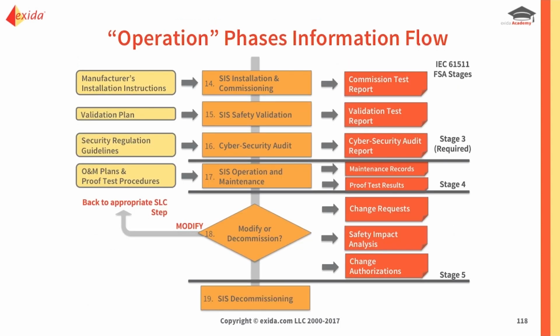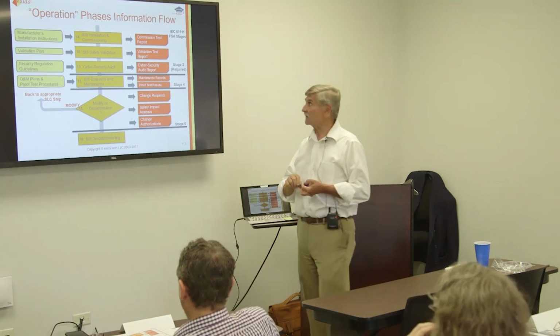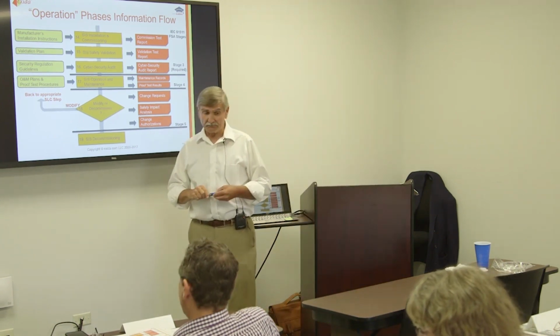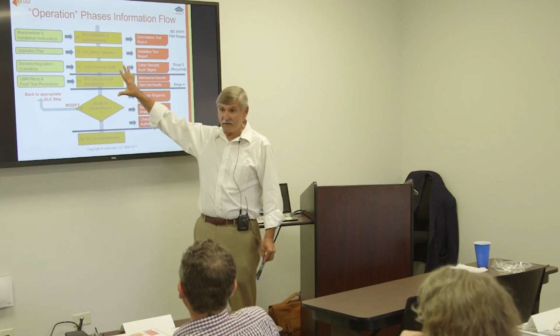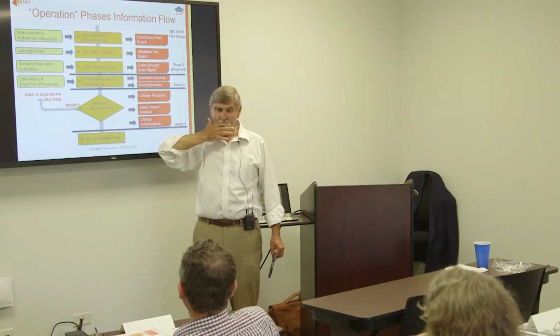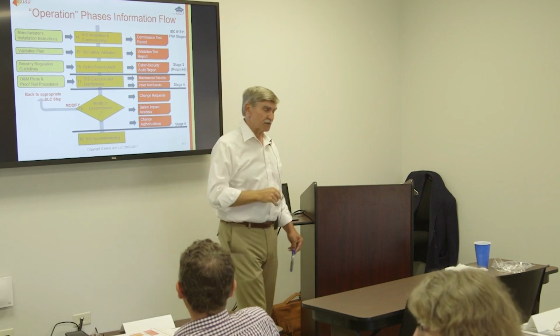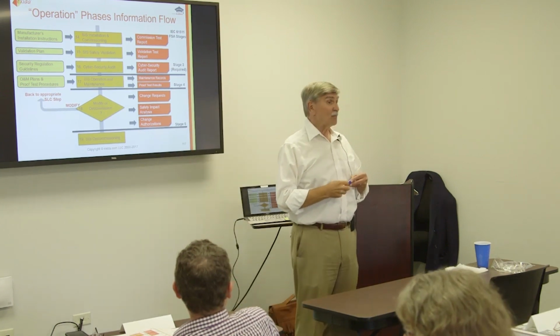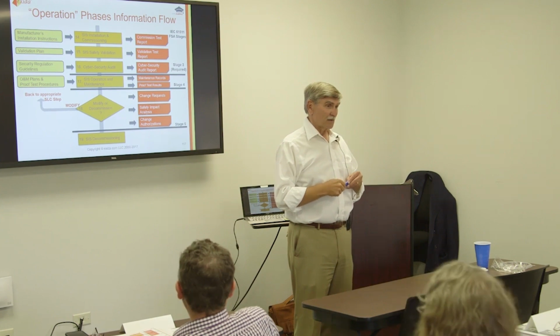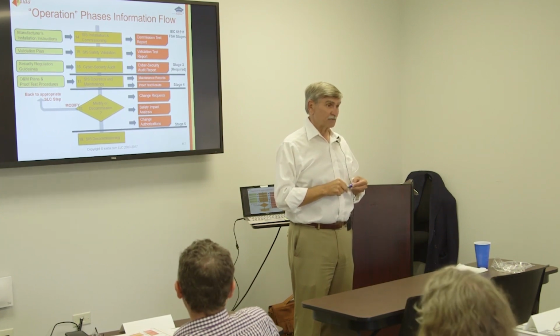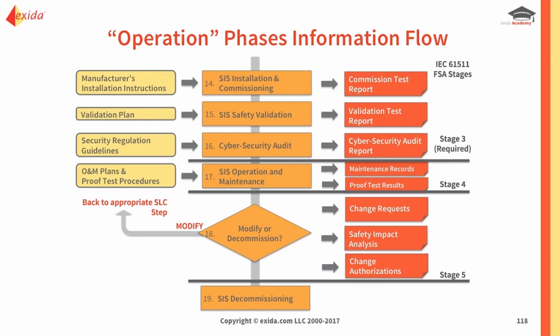61508 and the family of standards that go with it go all the way to decommissioning, which is good because this may be the most important phase of the entire safety life cycle. A really well-designed system will fail more frequently with bad maintenance practices. What I just said was failure rates change from site to site.